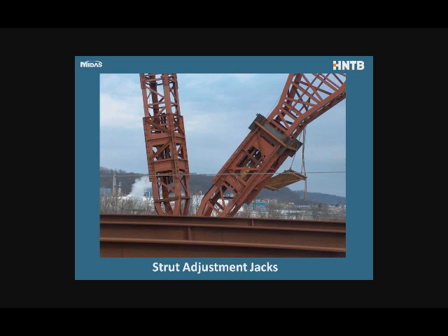I have a close-up view of the adjustment jacks, and you can see where they had a jacking mechanism where they could vary the length of these jacks. So this frame just keeps the two parts of the jack together, prevents it from moving naturally. There are four 4-inch diameter threaded rods in there and two large jacks.